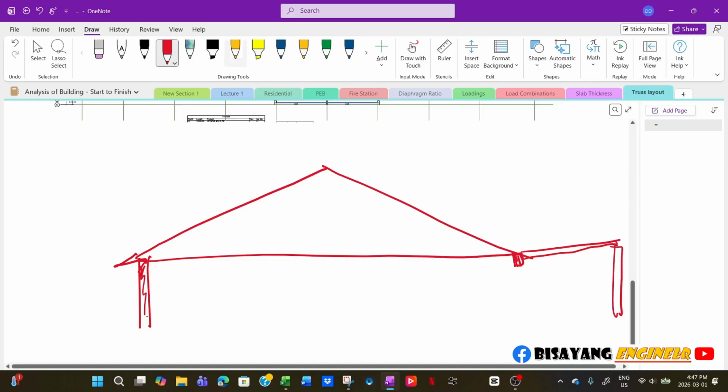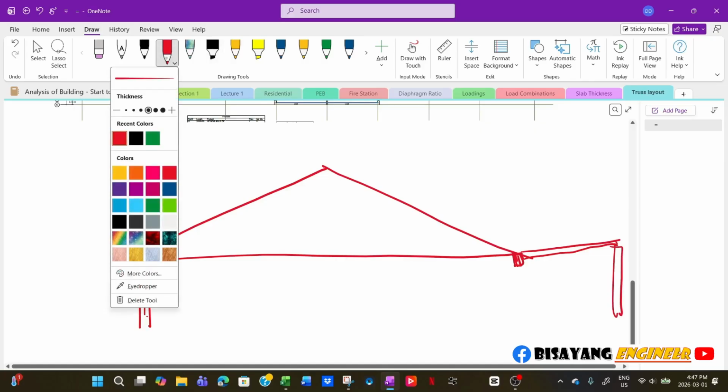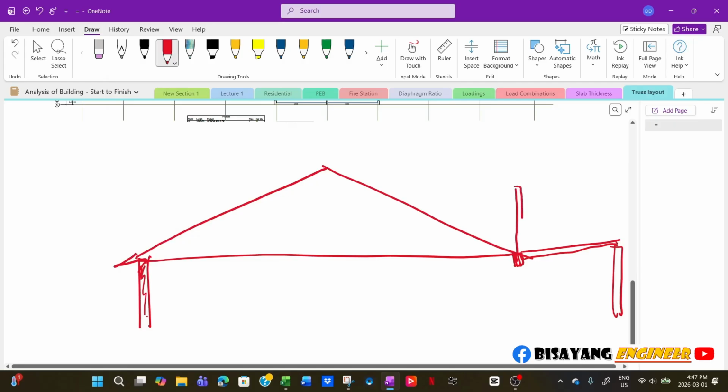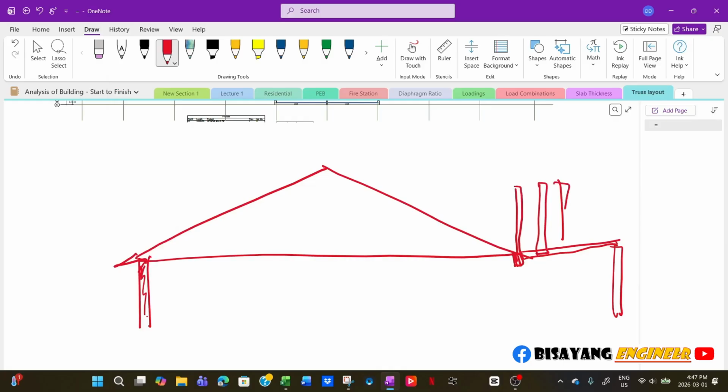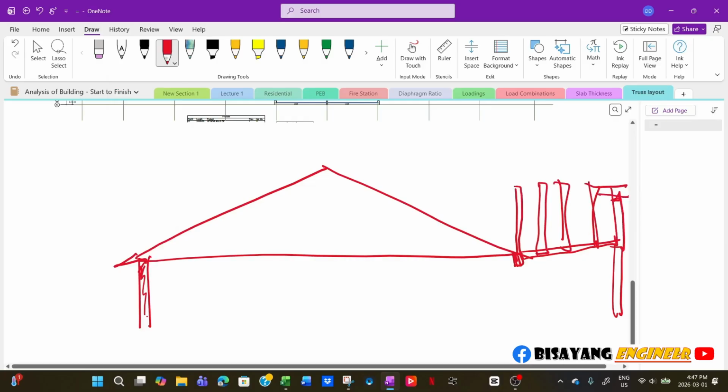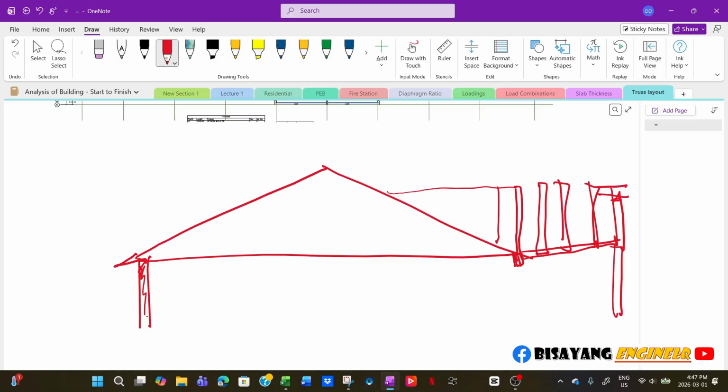And then on this side, this will be a full depth truss at 24 inches on center, and then you have your reduced end truss and then your outrigger. And then on this side, it is called the valley fill truss.